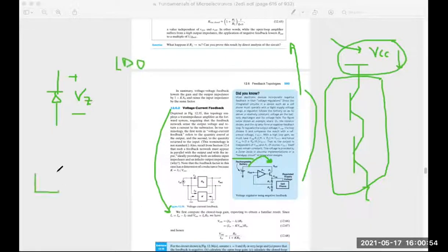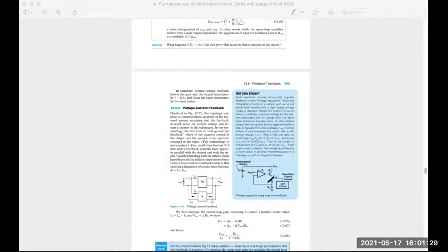So basically you have a battery, the output is connected to a circuit that will give you a stable voltage. For instance, this is a regulator. The battery is driving the circuit, for instance, but you have a Zener diode here, which provides a constant voltage. And connecting this amplifier and running this feedback, we make sure that this Vref is equal to this Vref, which is constant, so that this voltage is constant due to resistive division. So this constant voltage actually runs your cell phone, which is called regulated supply voltage.